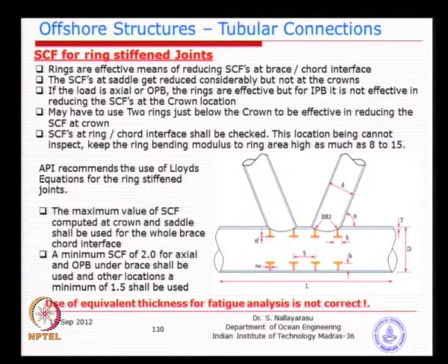Last time, for static connection design, we learned about reinforcing the joint because the chord wall thickness could not be increased for several reasons, which we discussed last time. And now we have a problem of failure, maybe due to large stress concentration factor, large stresses. Now, what we need to do is find alternate means. One of the means is to stiffen the joint, as we did for static loads. So, you could actually put a stiffener in this fashion, a typical arrangement, just to get an idea.